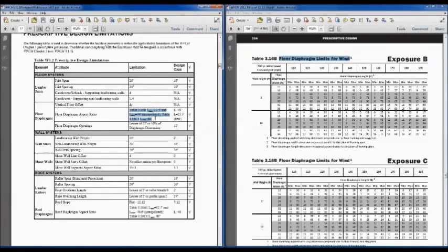So this little check here that we do comes from this table in the wood frame construction manual, but there's a lot of calculations from ASCE 7 that, as an engineer in the audience, I hope you realize if you've had to plow through ASCE 7 that we've done a lot of the work in calculating all of those wind loads and seismic loads and tabulating that information for you in Chapter 2. And then that carries over here into Chapter 3 to develop the limitations that we have for things like roof and floor diaphragms. So again, I'm not going to take time as we go through the rest to tackle all that background information, but that is what sits behind a lot of these assumptions.